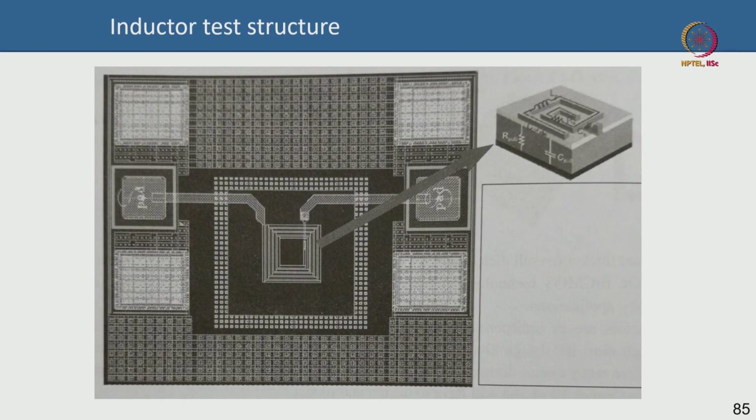Now when you have an inductor fabricated, you need to characterize it. You need to model it, verify the model against the characterization results, and iteratively improve to get to a robust model and characterized data. Once you have that, you do not necessarily need to characterize every time. You know the model and you will use that model as a part of something called a PDK, process design kit. It's a different thing, I'll come to that later if time permits. The foundry will give the PDK to the circuit designer, and the circuit designer will use that to design an inductor within a certain range.